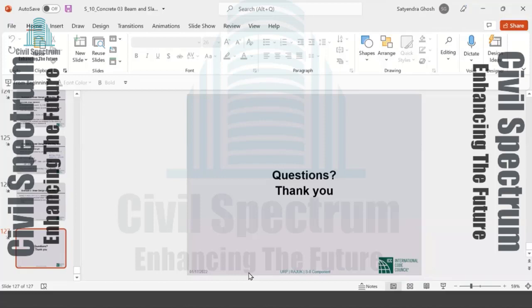So this is why, instead of going into that, take a look at the paper by George Barney, one of the four. I think there is quite a bit of good stuff in that paper. It's not one solution. If it's a tiny opening, it may not mean anything. If it is a little bit larger than that, we will just put rebars around. But then you want to pass HVAC ducts through a beam. It's a problem that you will have to deal with. So no, there is no one answer to that question.